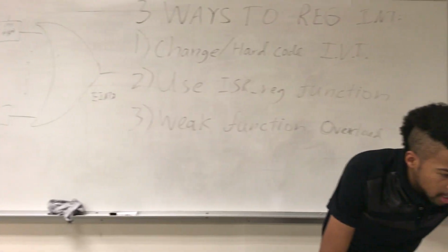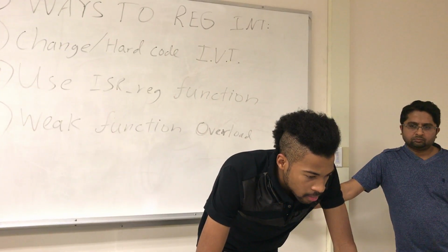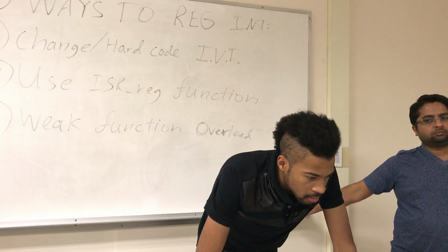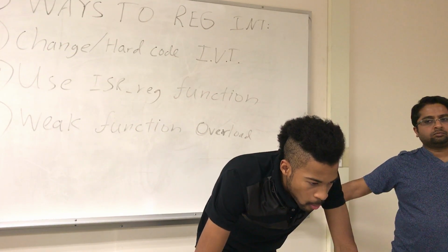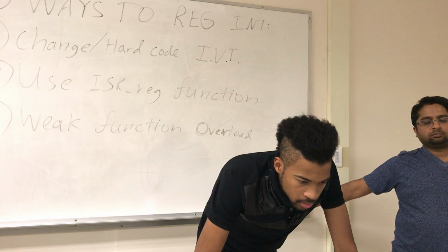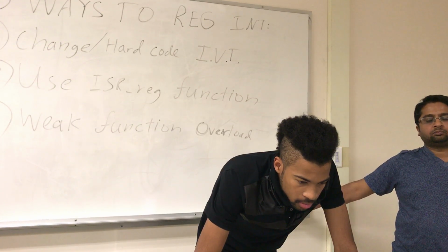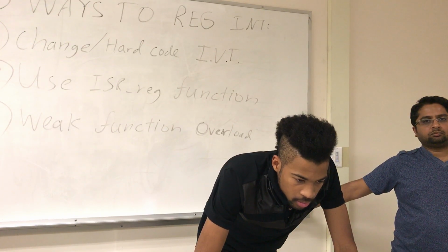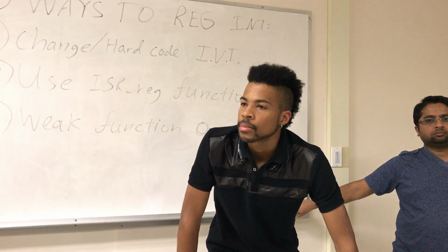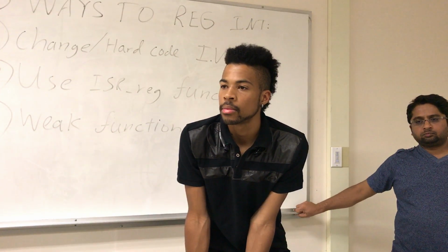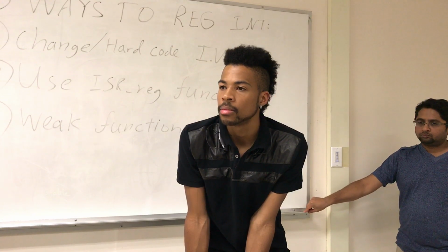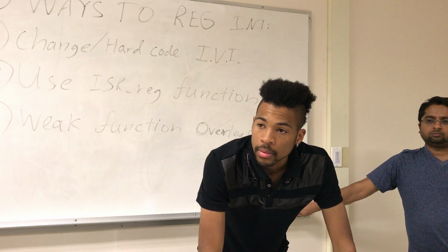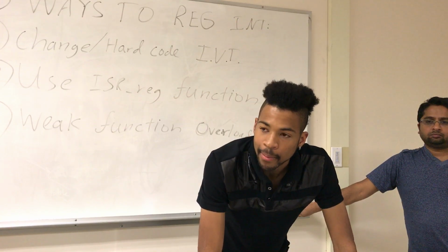So when we enable external interrupts on one of those pins, we're essentially allowing the edge detector to actually look for a signal on that pin. Repeat that one more time? When we enable an interrupt on a specific pin for a port, we're essentially enabling the edge detector such that that signal can go through to the OR gate. Yeah, pretty much.